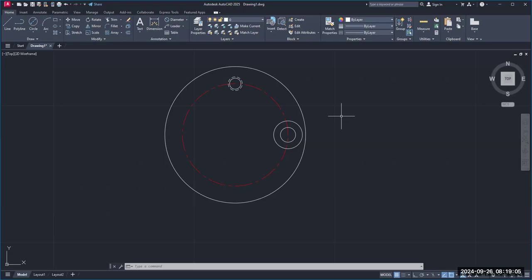That's okay. All right, now we're going to do the hole at the 6 o'clock position. This is a spot face hole. How do I know that? Look at the drawing I gave you. You will see a symbol that has the letters SF in there, spot face. It's very similar to a counter bore, but it's not a counter bore because you're only going down a little bit.